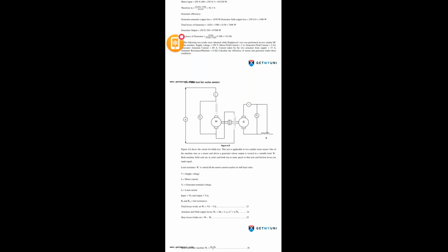And we are additionally using two ammeters, I1 and I2. Here I1 is the current flowing through the motor, and I2 is the current coming from the generator. Here I1 is based on the input current, and I2 is based on the output current. By using these 5 parameters, we need to find the input power of the motor and the output power of the generator. When both are coupled, they should work at the same speed with the same parameters.